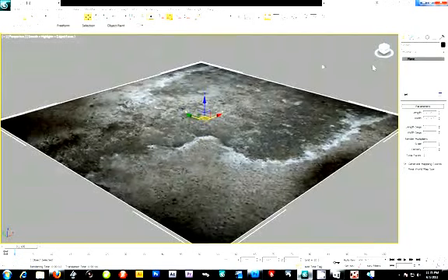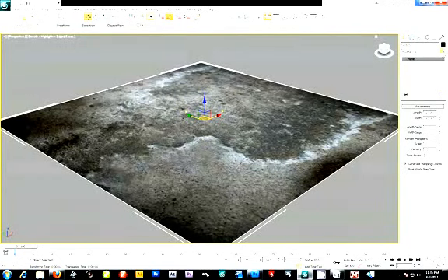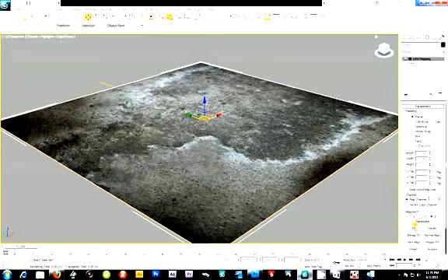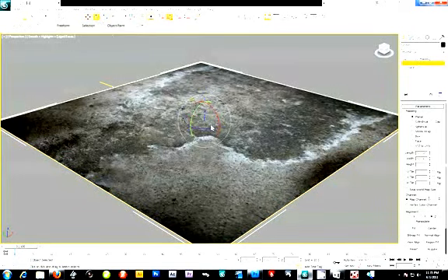So I'm going to go to my modify list, click it down all the way to the bottom, and you can see not unwrap, but the UVW map. I'm going to open that up, and notice I get an orange bounding cage on my object. And there, it's on my stack now. I got the gizmo. If I click that, I can actually rotate this onto the object.